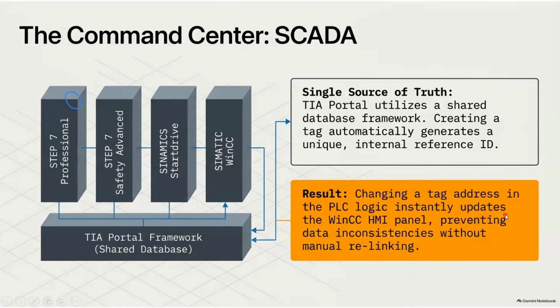Now here you can see changing the tag address in the PLC logic instantly updates the WinCC. This is the HMI panel. WinCC is a software name, and it prevents data inconsistencies. Previously, without this TIA Portal software it was difficult, but now it helps us in a much better way. If we change the tag name in one particular location, suppose Tank 1 is the tag name and you replace it with some other name, that name change will be reflected in all the locations where Tank 1 is used.